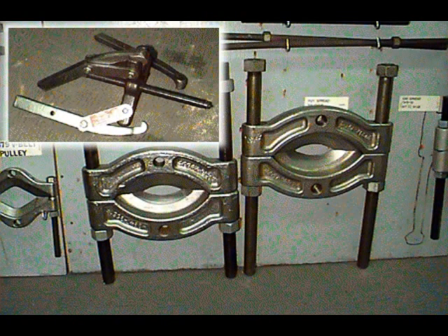Replacement of bearings is complicated, requires special tools, and should only be attempted by a qualified maintenance mechanic. Replacement involves using a bearing puller and requires proper handling, cleaning, inspection, and lubrication, as well as extreme care during replacement to avoid damage to the bearing or the shaft.